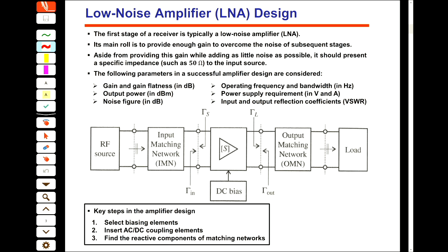And for the transmission line, usually we say the impedance is 50 ohm or 75 ohm, different values. But usually we say the impedance is purely resistive. So we need to design an amplifier with a purely resistive input impedance matching the transmission line that we select, which is usually 50 ohm.